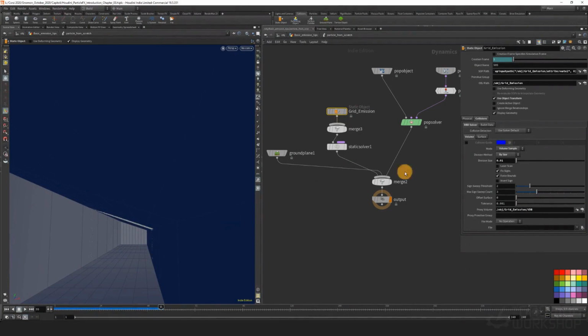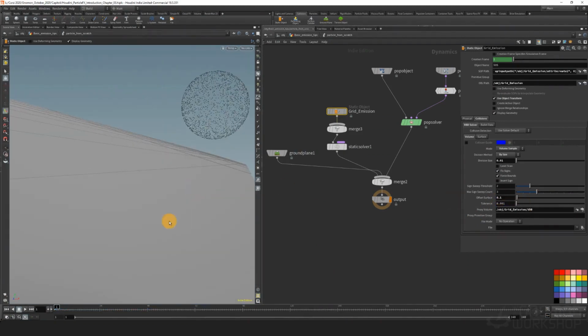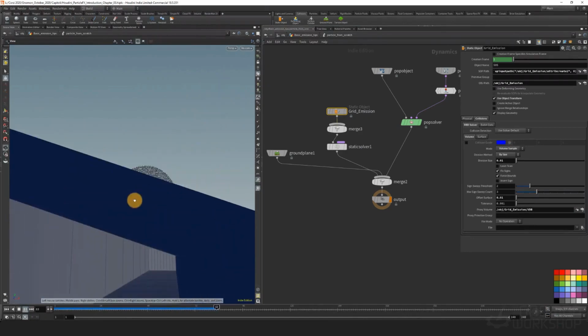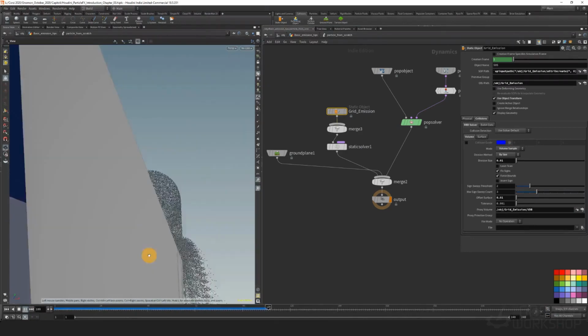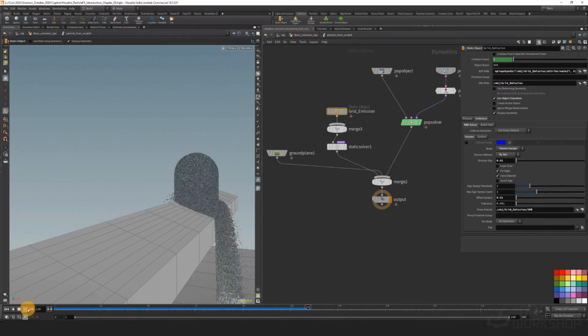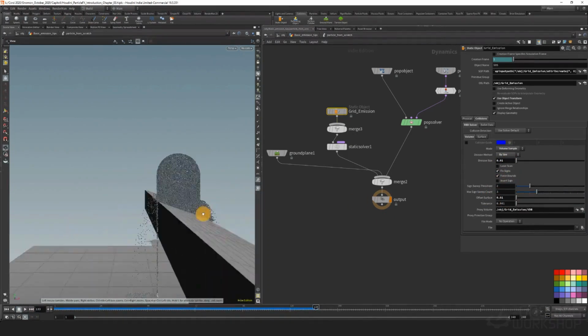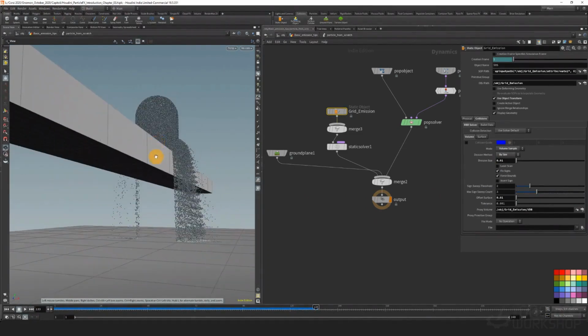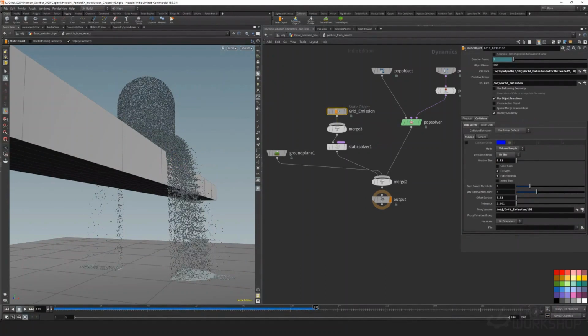It is really precise. By the way, if you like, you can have a little offset. Let's try with 01 to see what happened. You see that that's really high, so let's go to 1 centimeter. This is low, and we should have no visible particle inside. Okay, so you see we changed just the resolution of the collision. We have a little bit of offset to be sure that we have the right collision around, and that's all. It is working perfectly.